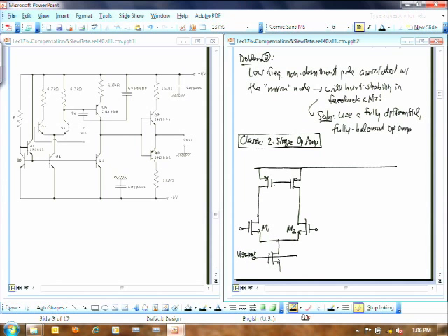That's the thing that, you may complain, oh, that's not enough voltage gain off of that. Here's VDD. And now what I'm going to do is, in order to supply my gain, I'm going to come out here and put another stage here. So I'm going to have a PMOS device here that's actually the driver device. I'm going to go down here to an NMOS device that is a current source load for the driver device that shares its V bias from the same node. So from the same V bias generator there to generate its current. Let me call this M6 and this M7. And this then is going to be my output.